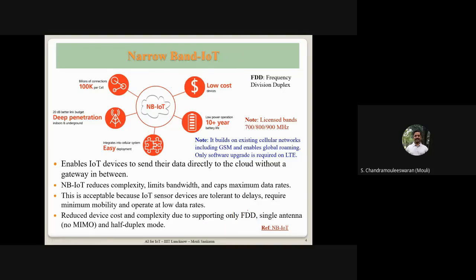So this device uses FDD, because time division needs lots of hardware built into the chip or IoT device to measure the time and then communicate during that time. So it consumes more power and increases the complexity of the device, whereas I mentioned that this is less complex. That's why FDD is used, wherein the choice of frequency is easier, whereas the choice of time is very critical and has to be very accurate. Frequencies also have to be accurate, but implementing them in the hardware is easier.